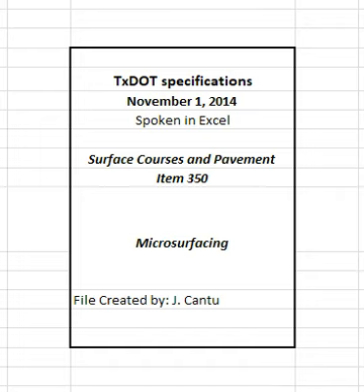Provide the engineer with representative samples of all component materials for verification. Notify the engineer of all material sources and before changing any material source or formulation. The engineer will verify that the specification requirements are met when the contractor makes a source or formulation change, and may require a new laboratory mixture design, trial batch, or both. The engineer may sample and test project materials at any time during the project to verify specification compliance in accordance with Item 6, Control of Materials.